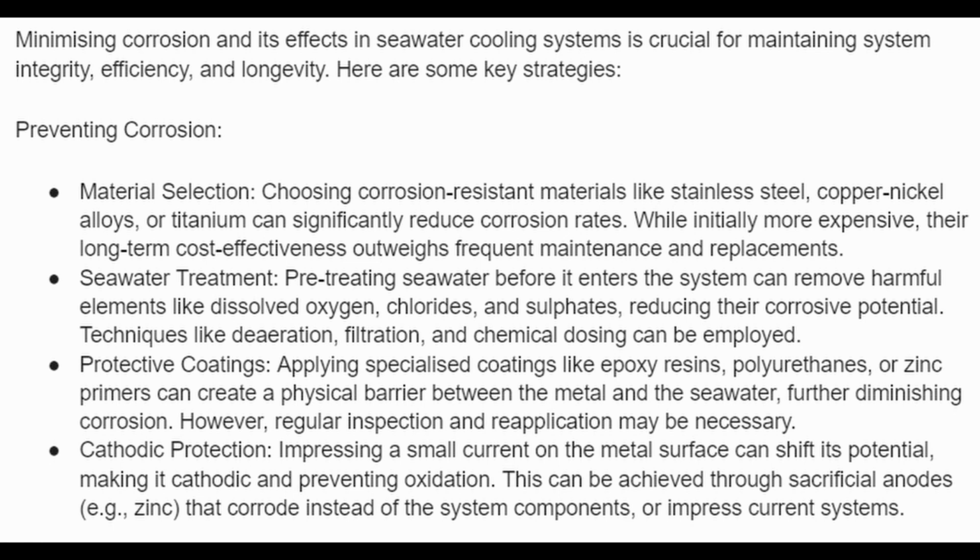Explain how corrosion and its effects can be minimized in seawater cooling systems. Minimizing corrosion and its effects in seawater cooling systems is crucial for maintaining system integrity, efficiency, and longevity. Here are some key strategies. Preventing corrosion by material selection, choosing corrosion-resistant materials like stainless steel, copper-nickel alloys, or titanium can significantly reduce corrosion rates.